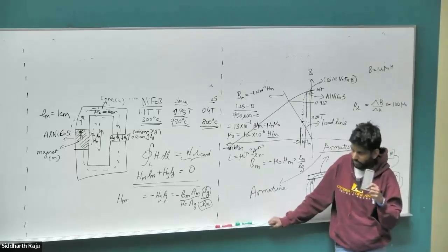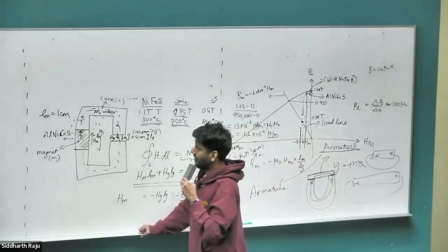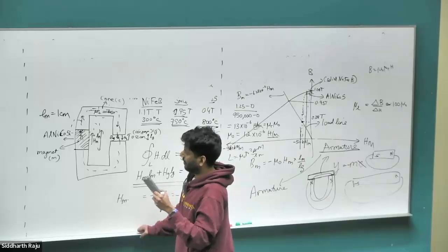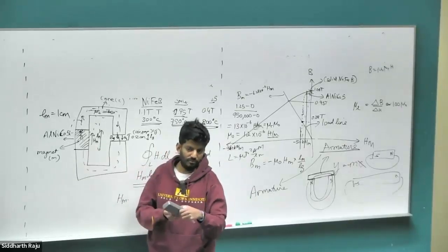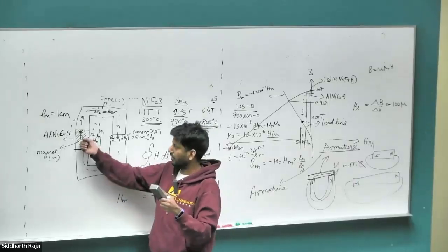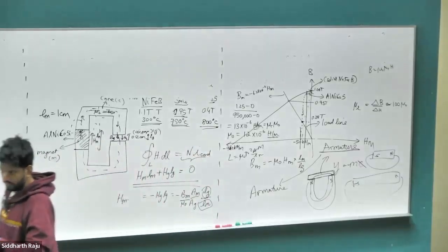That's a very big problem when we do motor design. You need to be careful when we calculate the air gap length and so on. When we look at the field lines, we cannot assume the magnet to be an iron material and assume that the field lines would prefer going through the magnet. In fact, the field lines would prefer going through the magnet just as much as they prefer going through the air gap. So depending on the magnet, that situation changes.